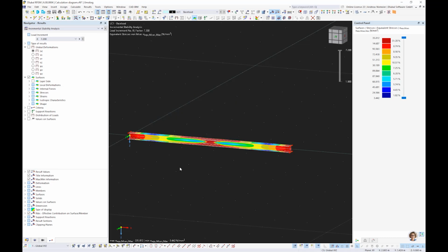Further, you have the same box of this factor here on this result part. You can watch all results. The result we're just seeing is the equivalent stress, so we have, let's say, the stress 235 here, the limit we define for yielding. What I like more is the criteria, because then I'm independent from the defined limit stress, so maybe yielding is defined with factor 1.